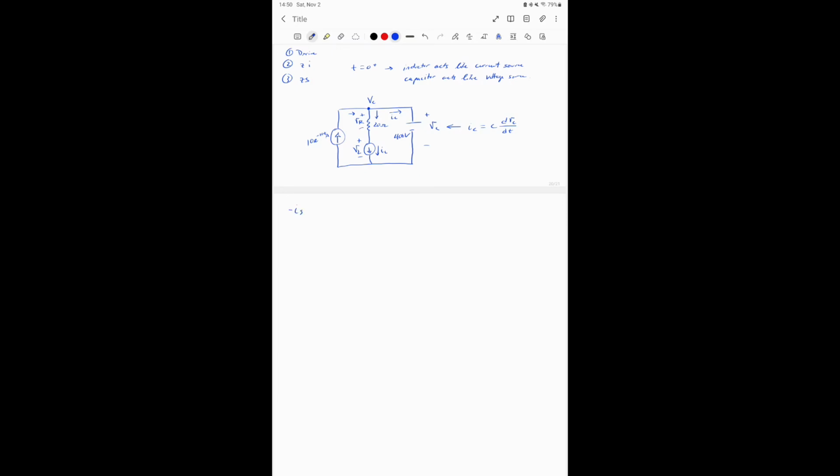So you have a negative I source, right? This is your source, plus your IR, which let's keep in mind, by the way, your IR is equal to your IL because they're in the same branch, right? And then plus your IC is equal to 0. And then we've got this equation already. So let's keep both of these things in mind as we move forward.